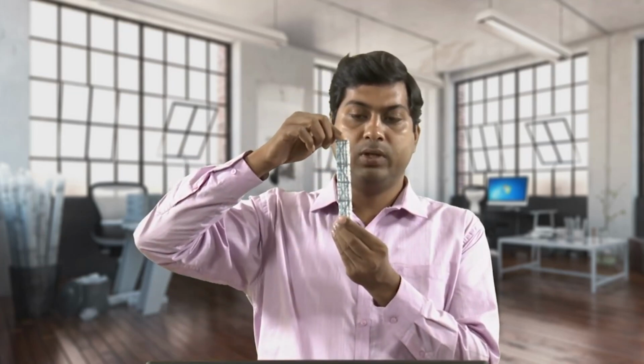Whenever we do the test with a concrete block under compressive stress, we see the development of cracks and it crashes. But when we apply load on a long column, where again I am repeating that the length is proportionally higher than the cross section, if you see carefully, when I apply load on it, it will first compress, then it will try to bend.